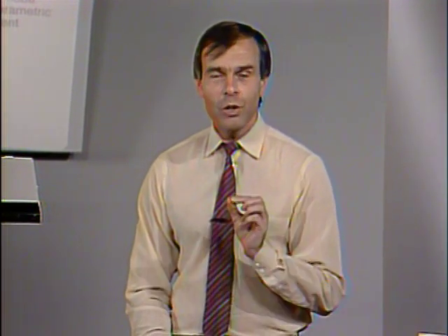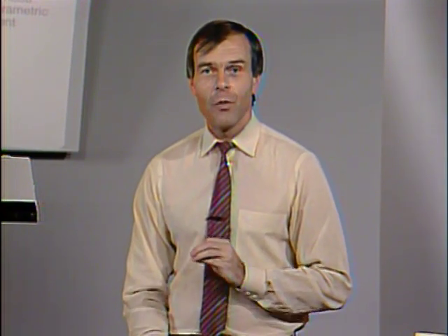However, a valid question certainly is to ask, how good is this number? After all, we used a finite element mesh to approximate the plate, a particular finite element idealization was used, and we have only obtained an approximation to the exact result. Well, to obtain insight into that question, to evaluate how good our analysis results really are, we can plot stress jumps the way we discussed it in an earlier lecture.